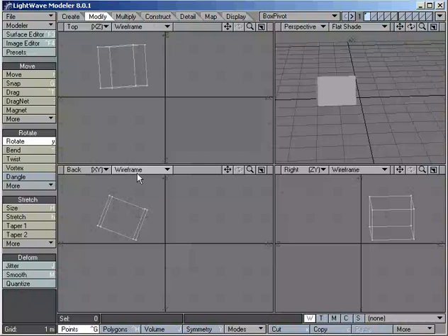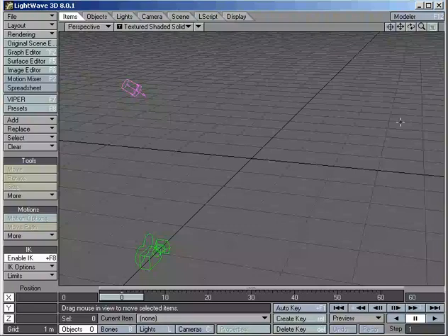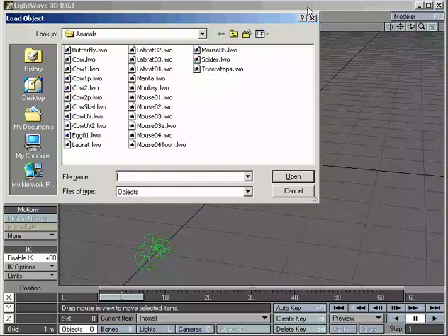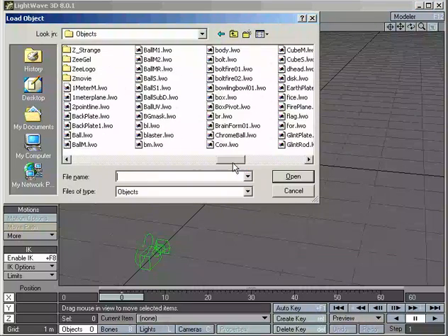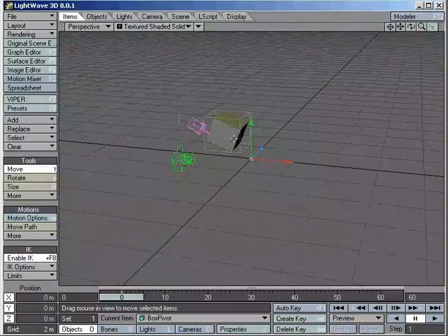And we'll jump into Layout. Use my hotkey, which is the plus button. And find box layout. There it is, box pivot. And we can see there's my pivot point.